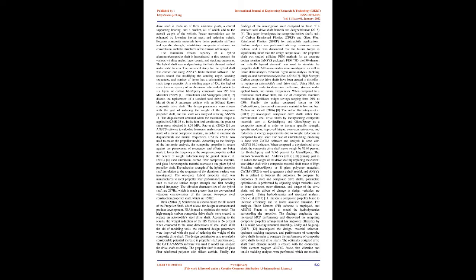The design parameters were chosen with the goal of reducing the weight of the composite propeller shaft, and the shaft was analyzed utilizing Ansys 11. The displacement obtained when the maximum torque is applied is 0.54 times 10 to the power of -3 m. In the identical conditions, the greatest shear stress obtained is 8.54 MPa.